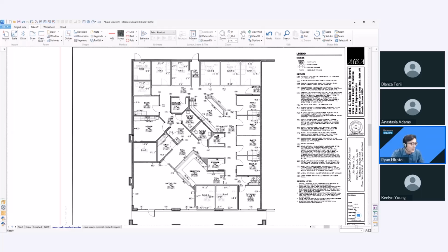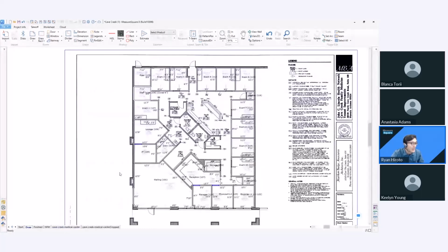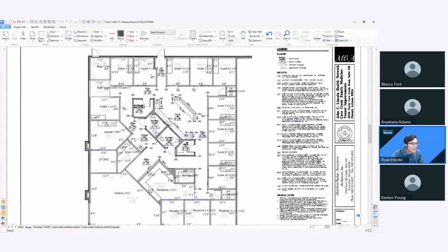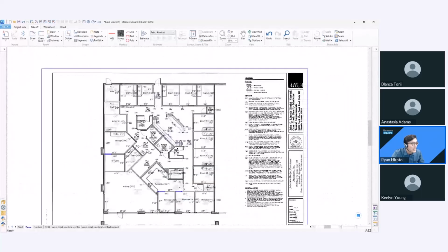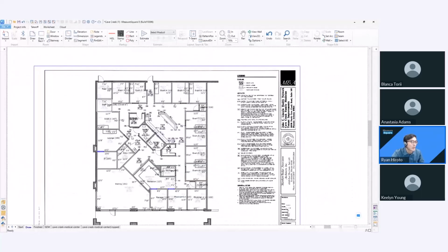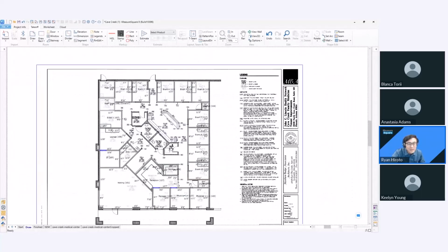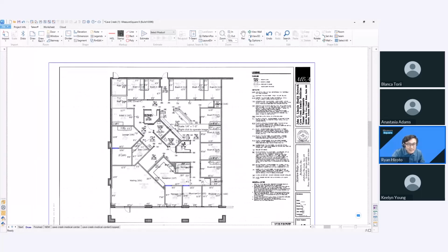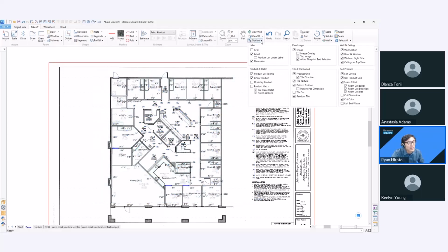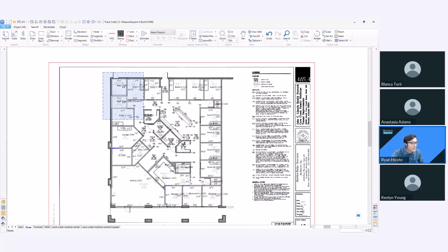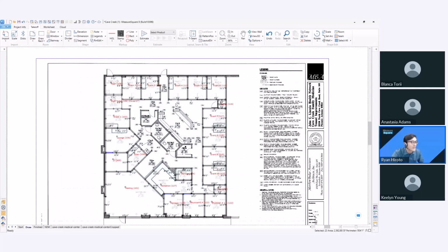It's our autocomplete. So moving from this room here, I have an already pre-drawn area to show. You can see here we have all these rooms drawn already, and we have this larger interior corridor that is not. So what our autocomplete can do for you is, if I select all these rooms, or let me do this really quickly, I'm going to go to my options here and turn off a little setting so that it's a little bit easier to see. So if I select all my rooms here, you can see them now all highlighted red.